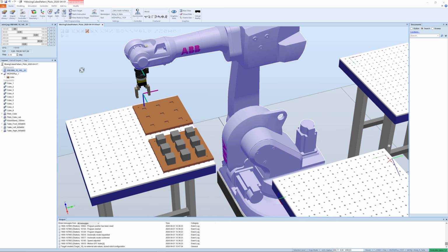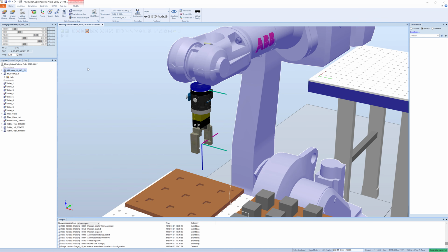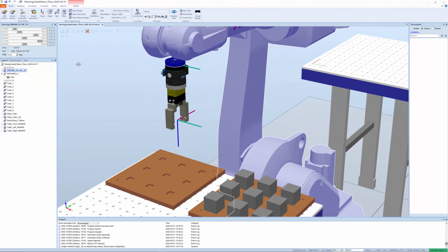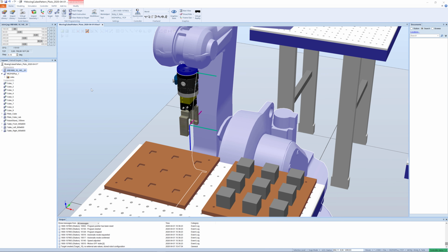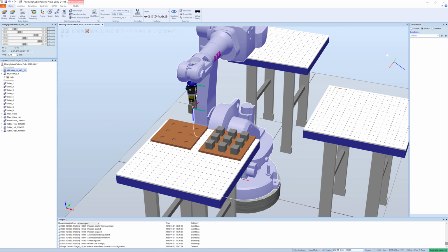This is pretty fine, but then we should be aware of how we are going to pick those objects. Obviously we are going to do it by rotating the 6th axis 45 degrees. You will see that in a short minute. That means that we do this right away in this kind of position, and then we will be in a good position to do this kind of manipulation.